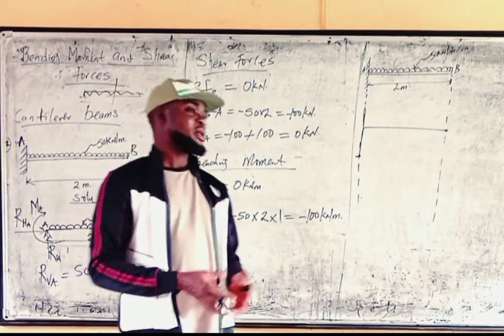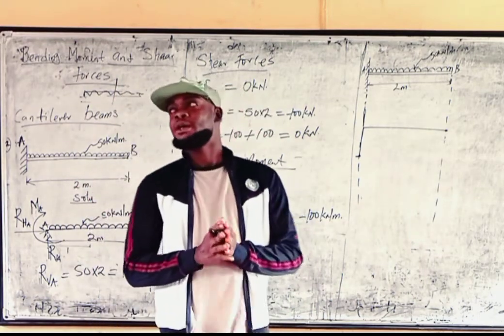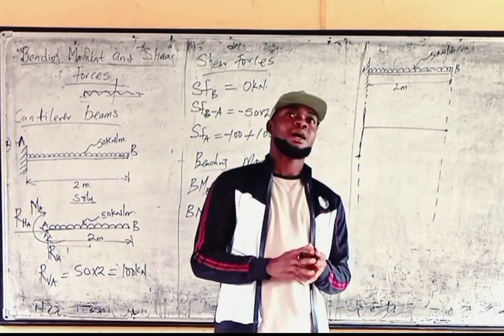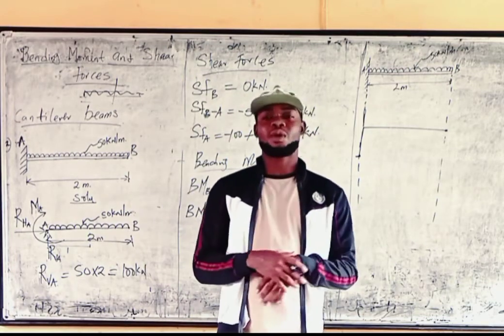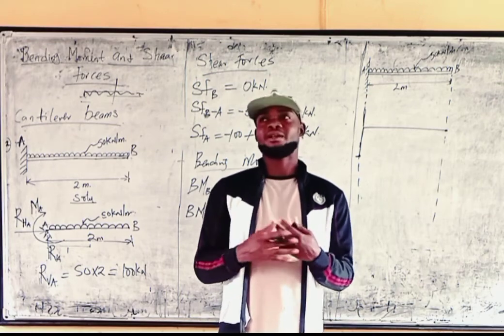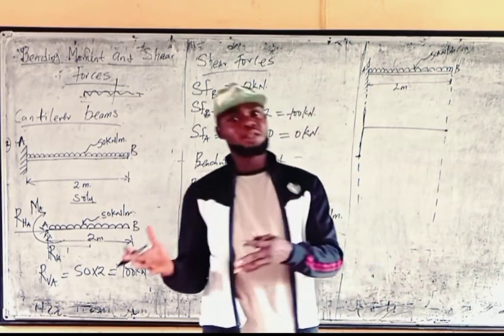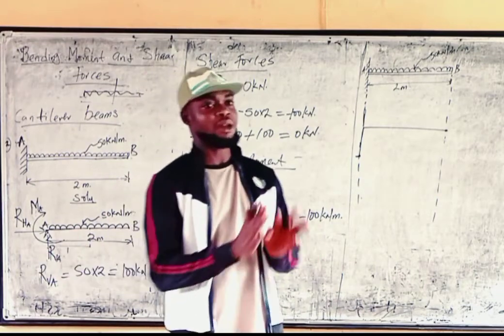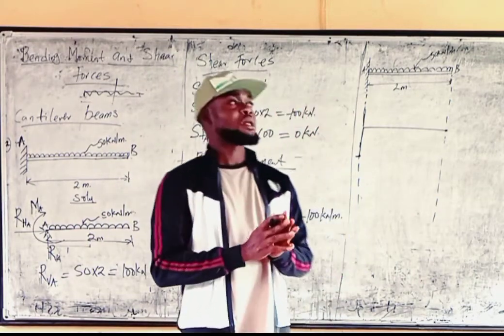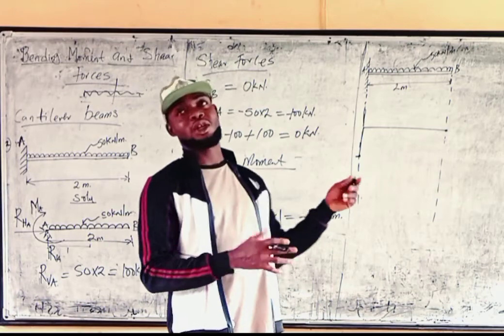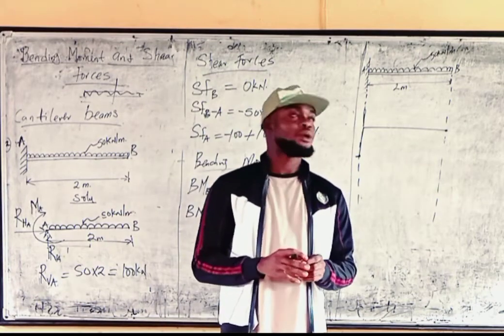You are drawing the bending moment. If you draw it that way, that will give us a real structural application or knowledge of what we are doing. So that will be very nice. But you can also draw the positive on the positive side and the negative on the negative side. It won't change anything. The value of the moment will still be the same. But the other one will just give us a real structural view of what we are doing.